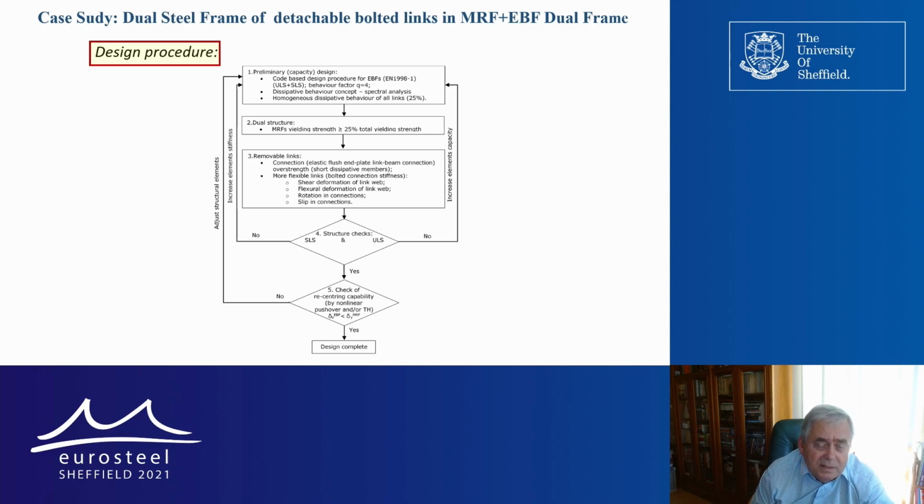And we must pre-qualify the link capacity of deformation. And at the end, of course, we need to check the recentering capability, but this is also not difficult to do.